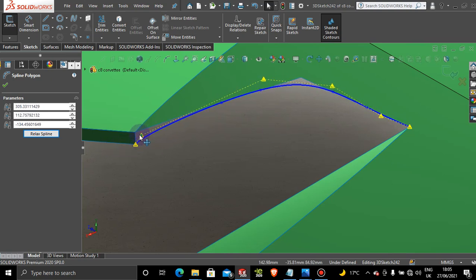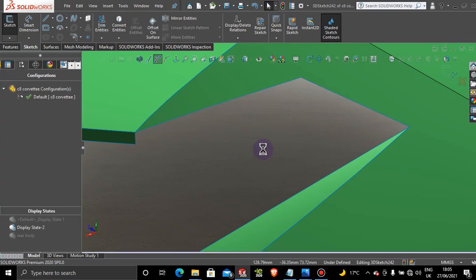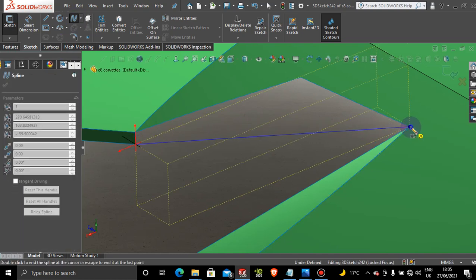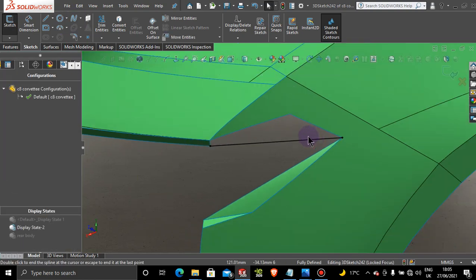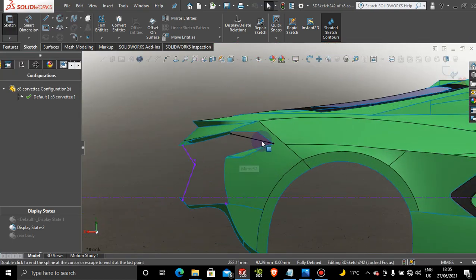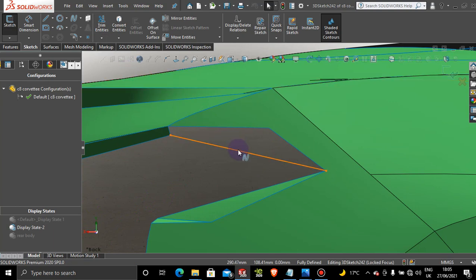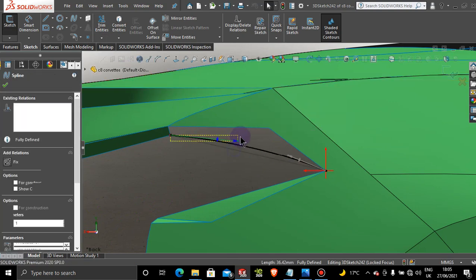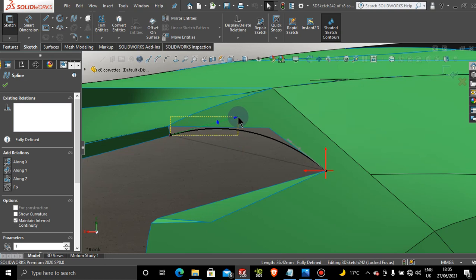So, because we snapped onto the surface, it's giving us these unnecessary curvatures, which is this one here. So I'm going to delete it. And instead, let's do a spline from this corner to this corner. Let's pull that spline up into position without adding any extra spline points.